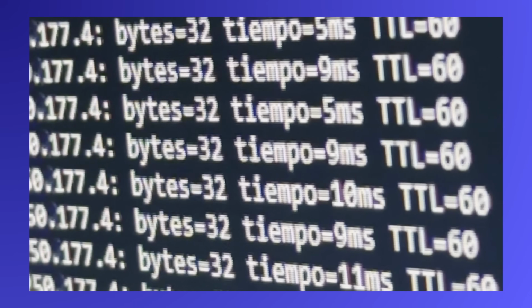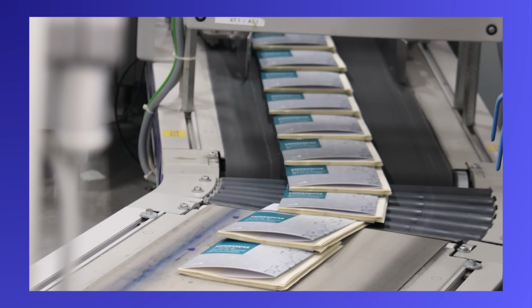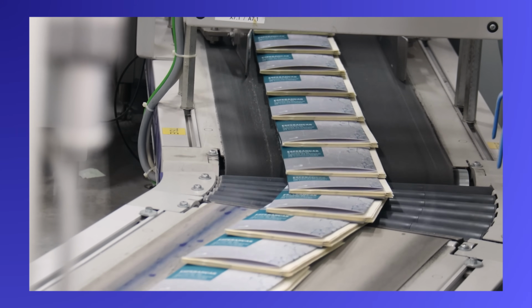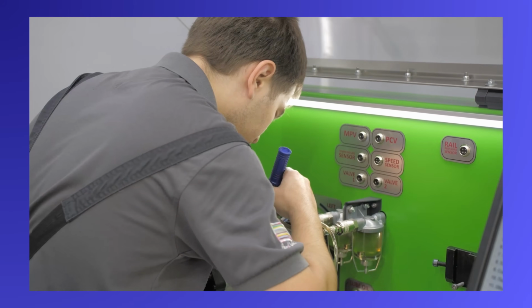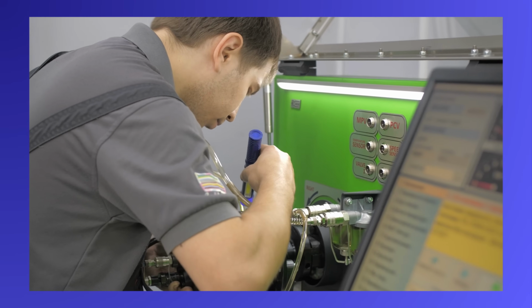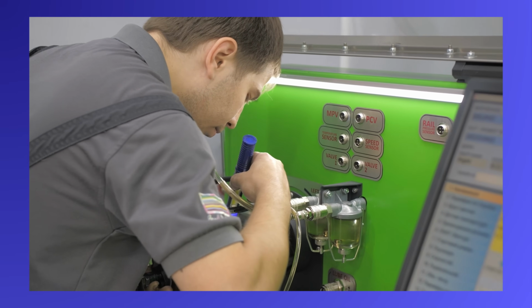For a variable like a production counter that increments every few seconds, subscription-based modalities mean that you're getting every change without unnecessary polling overhead. For a variable like machine state enumeration that changes infrequently, you're not wasting network capacity sending the same value over and over again. And that, with all the other additional meta-contextual information, gives you the ability to send sparse amounts of data while still communicating a ton of information.